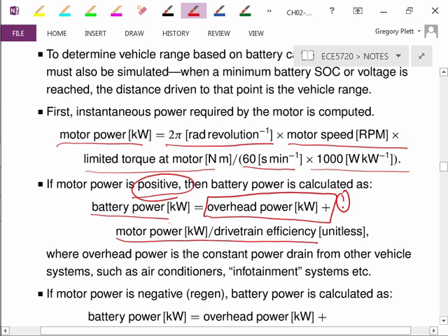And by the way, some of the more advanced things people are looking at for controlling electric vehicles is to control things like air conditioners, such that instead of being fully on or fully off, they have a kind of pulse width modulated or different speed settings. So the air conditioner can be turned down a little bit at different times and turned up a little bit, so that you maybe lose a little bit of your command authority over cabin air temperature, so it's not quite as perfect as you'd like, but it really benefits your vehicle range and economy.